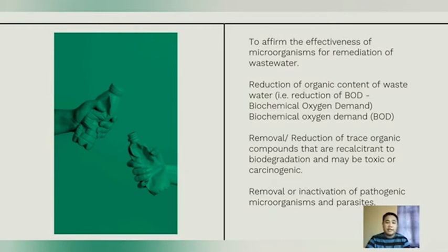Secondly, the reduction of organic content of wastewater, for example, the reduction of biochemical oxygen demand. Next is, of course, removal or reduction of trace organic compounds that are recalcitrant to biodegradation and may be toxic or carcinogenic. So, as I have said, it might be very dangerous to our health. And then, of course, the removal or inactivation of pathogenic microorganisms and parasites.